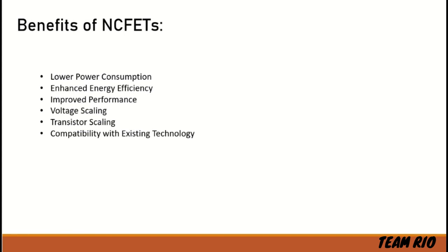Then enhanced energy efficiency. The steep subthreshold slope achieved by NCFETs results in better energy efficiency. Devices with NCFETs can switch more efficiently between on and off states, reducing energy dissipation during transitions. Then improved performance. NCFETs can offer high drive currents and faster switching speeds due to the effective voltage boost provided by the negative capacitance effect.